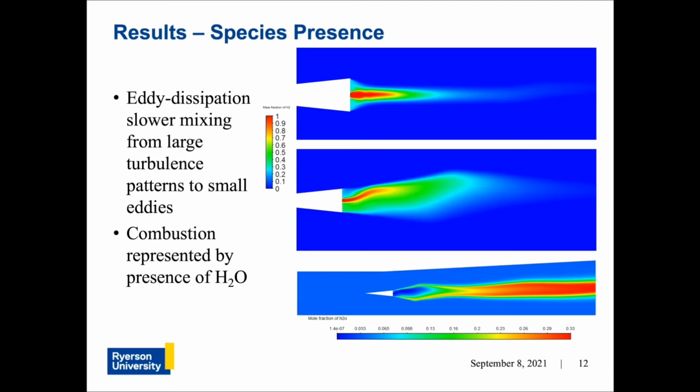Turbulent kinetic energy contours are comparable to the hydrogen mass fractions. The high-energy initial hydrogen stream that separated the 2 recirculation regions in case 3 can be seen here. It is more streamlined than the combustion model in case 4, where the small dispersed eddies are more influenced by the expansion area in the combustor and flow slightly upward, including more concentrated regions of the hydrogen stream.